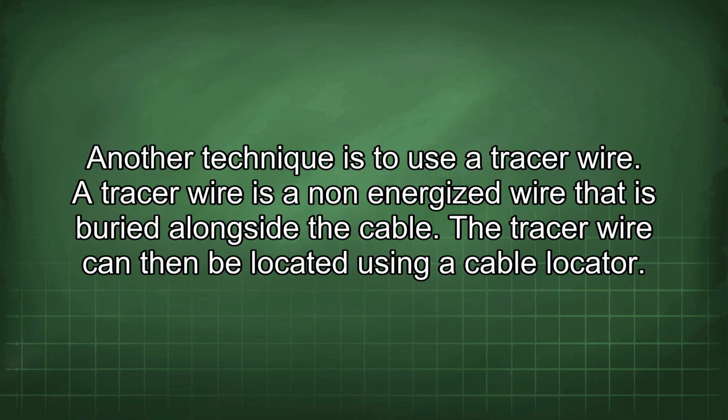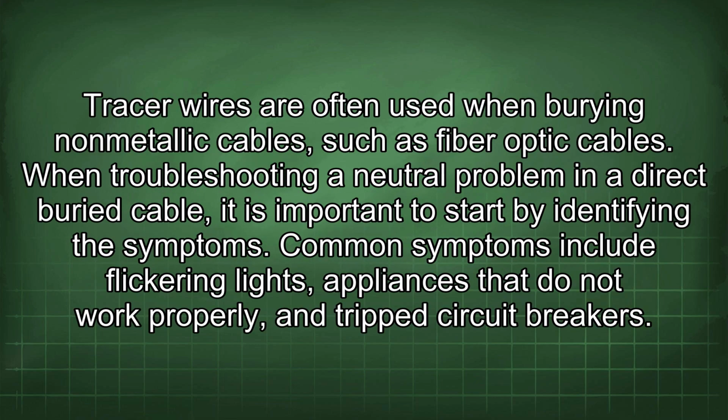Another technique is to use a tracer wire. A tracer wire is a non-energized wire that is buried alongside the cable. The tracer wire can then be located using a cable locator. Tracer wires are often used when burying non-metallic cables, such as fiber optic cables.